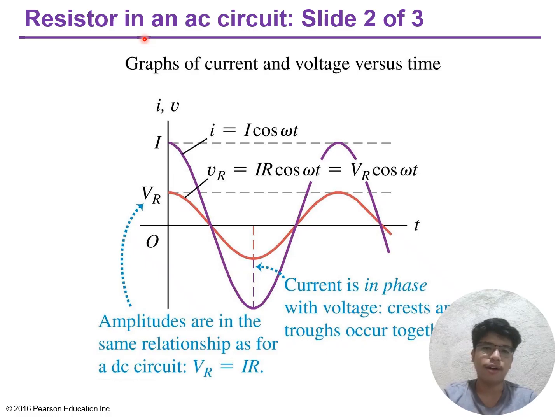reference axis. The horizontal placement of these phasors at angle 0 degrees indicates zero phase difference, a characteristic unique to resistive loads. If we express the voltage as v(t) equals capital V times cosine of omega t, and the current as i(t) equals capital I times cosine of omega t, where both have the same phase angle, we see mathematically why the phasors align perfectly.